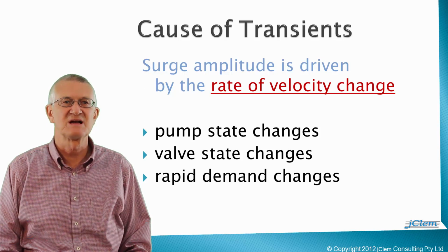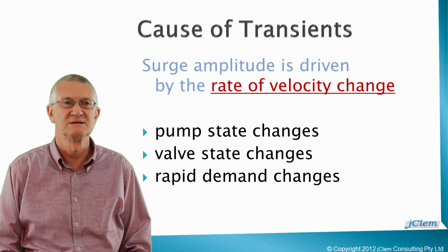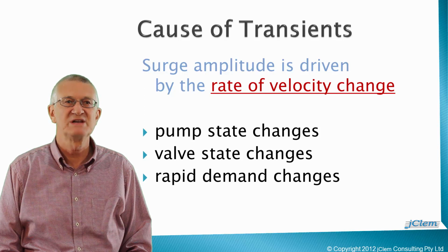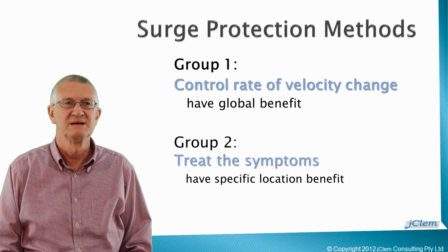Thinking about customer sites which can generate larger flow rates, for example a process plant, a fire protection system, or a landscaped irrigation system, their changes in demand are driven by a pump starting or stopping, or a valve opening or closing. Consequently, your engineering career is likely to include protecting systems from pressure surges created by the operation of pumps and valves. Let us take the next step by looking at a list of possible surge protection methods.